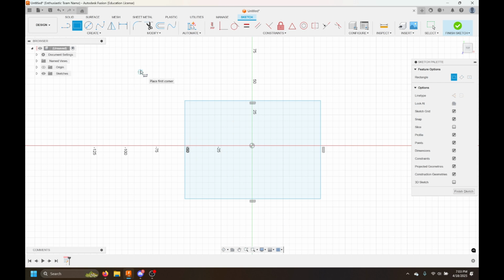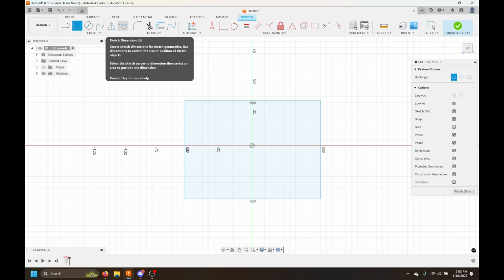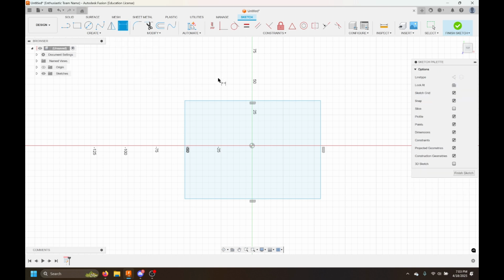This button right here is the sketch dimension button. It's very versatile. You can grab this edge, or you can grab between 2 points and take that dimension, or depending on where you put your mouse, it'll do all sorts of different ones. So we're just gonna do these 2 different edges dimensions. This part, you can get an idea from the size of it. It is 2 inches on this face. Oh, I'm in millimeters, hold on. Are you in inches or millimeters? Millimeters.